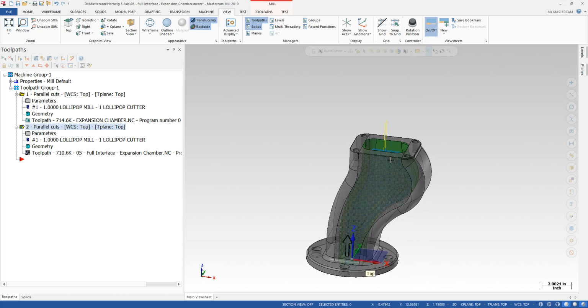So this is just an example of how I approach all toolpaths in general, whether it's drill, whether it's contour, multi-axis, 3D toolpath. What do I want the toolpath to do? How the motion or the CNC machine I want to control. And then I worry about what I want the shank to do or how much motion I want to control. And then I worry about my collisions later.